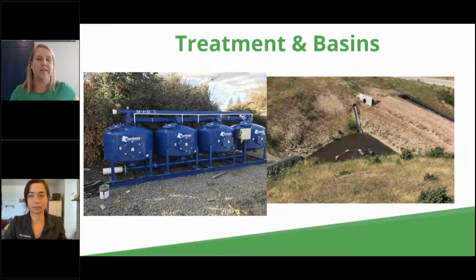So if you have these on your site, they require annual maintenance. So, the sediment basin, if it's doing its job, it's filling up with sediment over the course of the year. So you need to make sure you come in regularly, definitely late, usually like July, August, and clean it back out before the next rainy season.